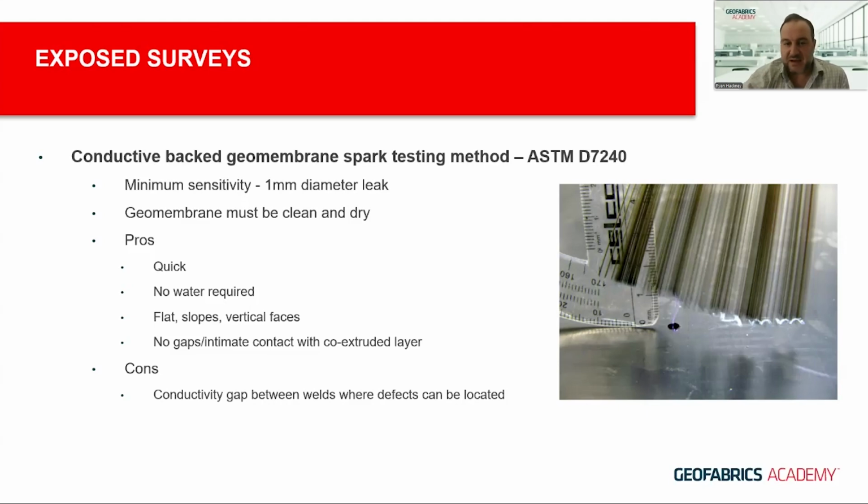The cons are that you can have a conductivity gap. So when you fusion weld or extrusion weld the membrane, you're potentially removing that conductive layer on the underside of the membrane. So there's certain procedures that need to occur to enable continuity between the welds.